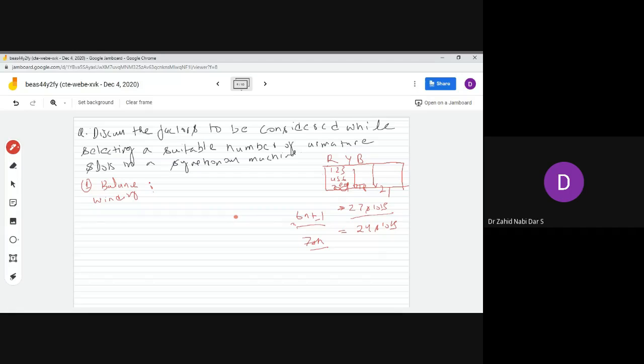Although the machine will operate, if you start an induction motor with three phase and remove one phase, the machine will still operate with two phases with a reduced rating capacity. But it will lead to overheating due to the unbalance produced by the removal of the third phase.